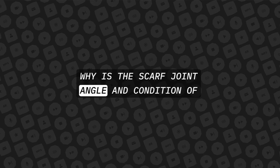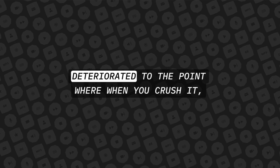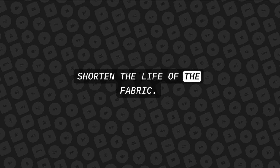Why is the scarf joint angle and condition of wood spar repair important? Strength of the repair. What is the term for a piece of wood that has deteriorated to the point where, when you crush it, it will turn into a dry powder? Dry rot. Pre-preg fabric in a freezer with a defrost cycle will do what? Shorten the life of the fabric.